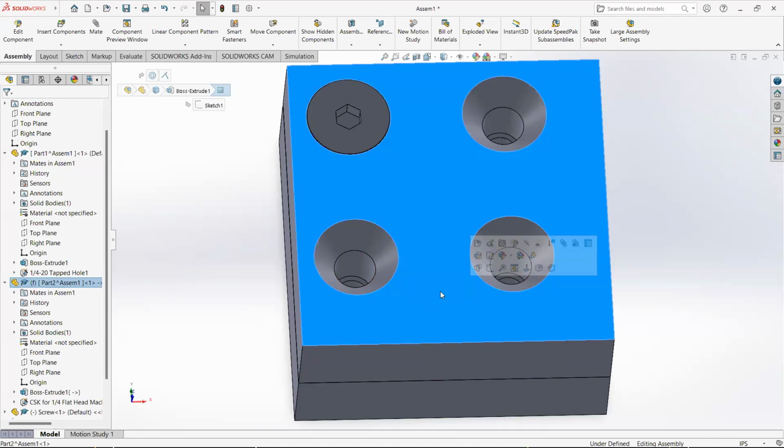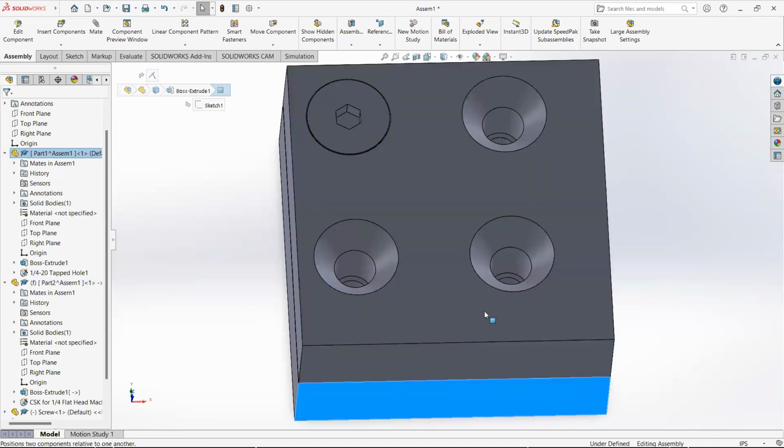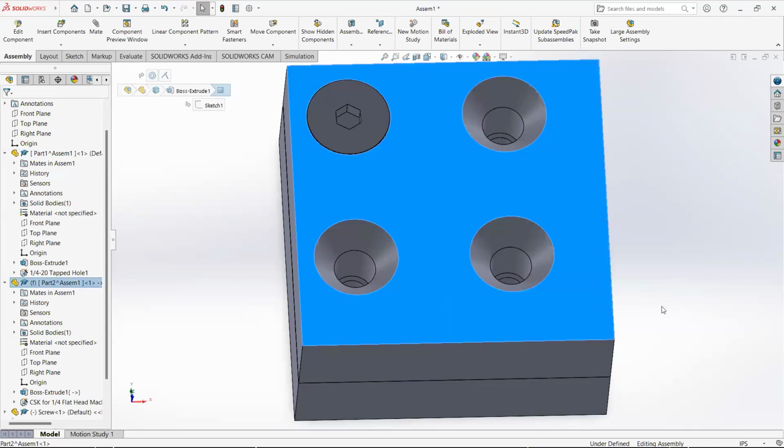And this isn't necessarily a problem with a two-plate assembly like this, but with hundreds of parts, if everything is in context, these changes can really cascade from one part to another, and it becomes a revision control problem. If I change one part at the base, every part above it is going to get changed by default, except I don't know what actually changed, and it really leads to problems when these parts come out of CAD and go into the physical world.